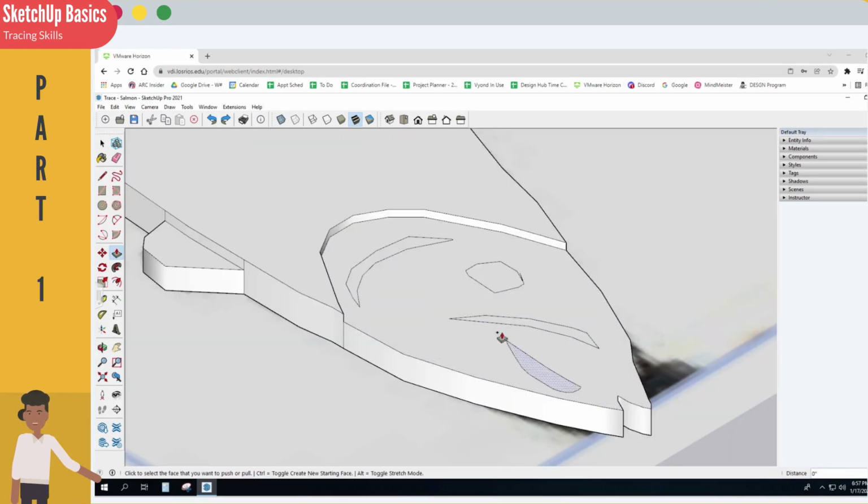Here you see that the press-pull tool works in both directions. This is your first view of positive, up from the surface, and negative, down into the surface, shapes. Once the region has been selected, and the press-pull direction has been set by the mouse, the exact dimension can just be typed in. It shows up in the lower right-hand box.